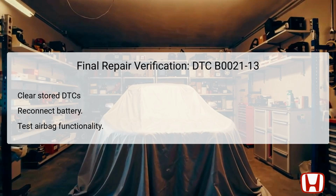Subsequently, the battery terminal must be reconnected to allow the SRS unit to receive power and perform its self-checks. Once these actions are complete, a comprehensive functionality test of the airbag will confirm whether the repairs were successful, ensuring that all safety systems are operational and meet their intended purposes. This final verification ensures that the vehicle is safe to operate moving forward.